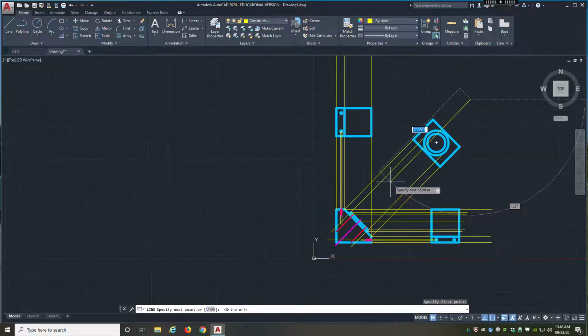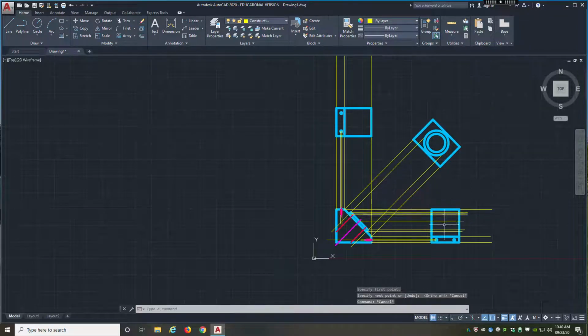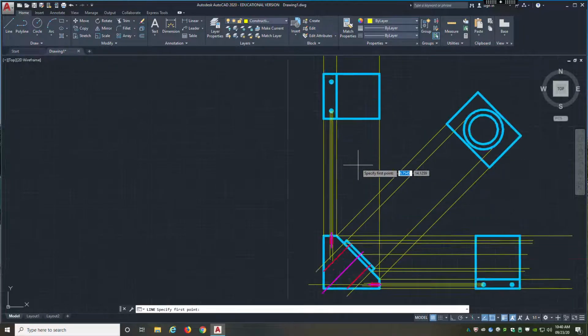And then you would bounce from your right view up off that miter line and into the top view and vice versa. But because we have the auxiliary view, we don't necessarily have to do that. But I do want to finish putting some of the other information in.